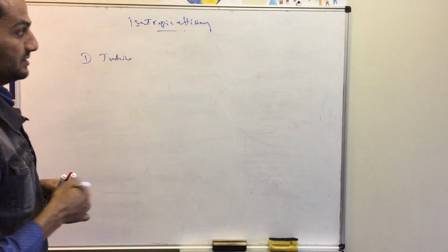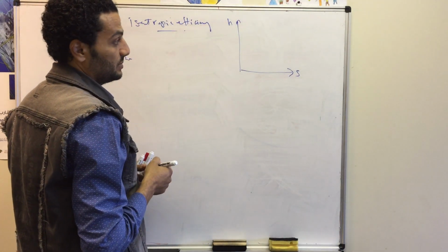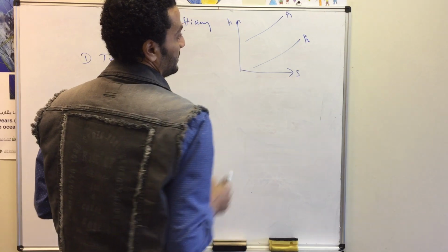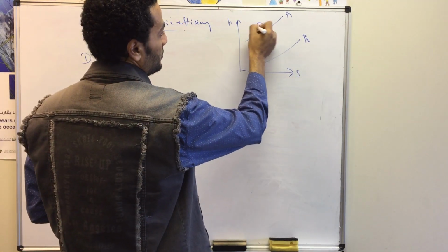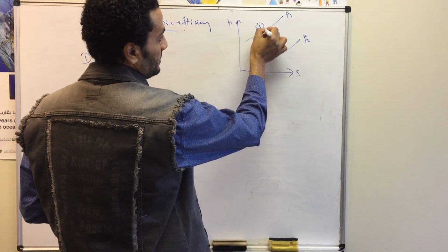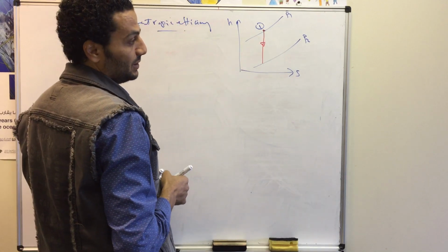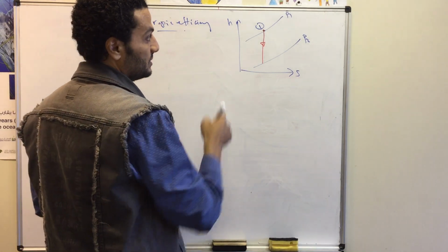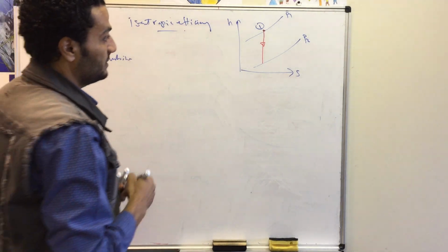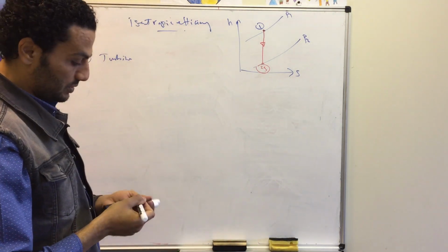The process through the turbine, as you know, is an expansion process from high pressure to low pressure. So let's look at this process on the h-s diagram. The input pressure to the turbine is P1, leaving at lower pressure P2. Let's say point 1 is at the inlet of this turbine. If this process through the turbine is isentropic, isentropic means delta S equals 0, so S is constant. The representation on the h-s diagram will be just a vertical line. The exit point in this case we will call 2s, which is the isentropic exit condition.